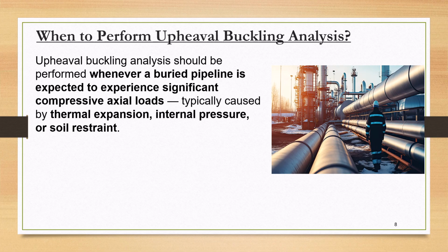Next is when temperature or pressure changes significantly during operation. Again, when terrain profile or soil conditions are unfavorable to upheaval buckling. Next is during construction or installation modifications, to reassess the upheaval buckling potential.